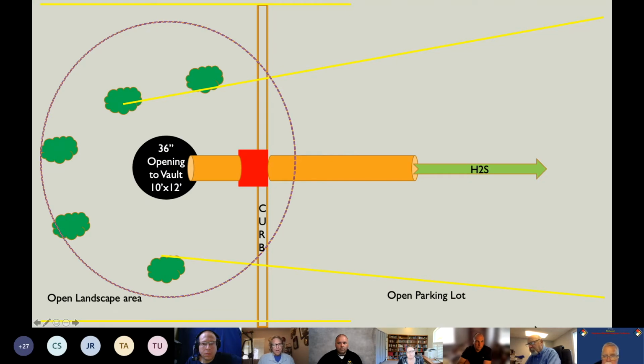Okay, so this is in August. Obviously, we know H2S, its properties indicate that it's going to hang low, but being that it's 110 degrees out, it's going to gain that kinetic energy, and obviously it came up like it did. So what's the problem with that at 200 parts per million at the opening? Well, the problem is that's twice the IDLH. So one of the things we immediately had to do is develop a hot zone for us.